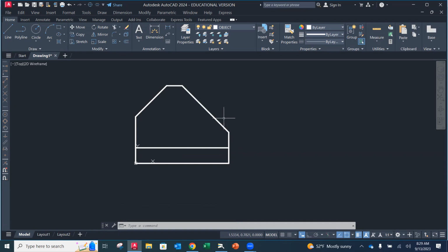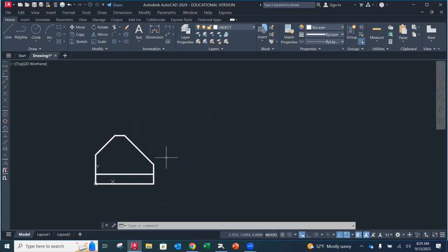So now what I'm going to do is create, you can pick, it could be the top view, it could be the right side view, whatever. I'm going to look at the top view. So I'm going to go up, and I'm going to make everything in line. Make sure that your snap references are showing. When I hover over the top of this extension, I get these green lines, because that way I can follow those up and I know that I'm in line with the feature that I just referenced. So I'm going to go on this left-hand side.